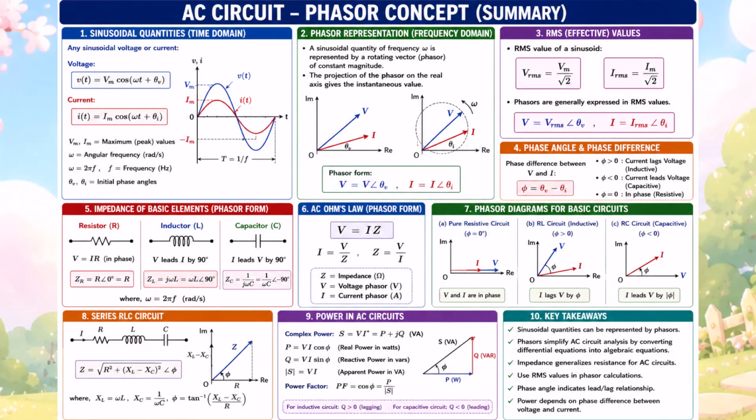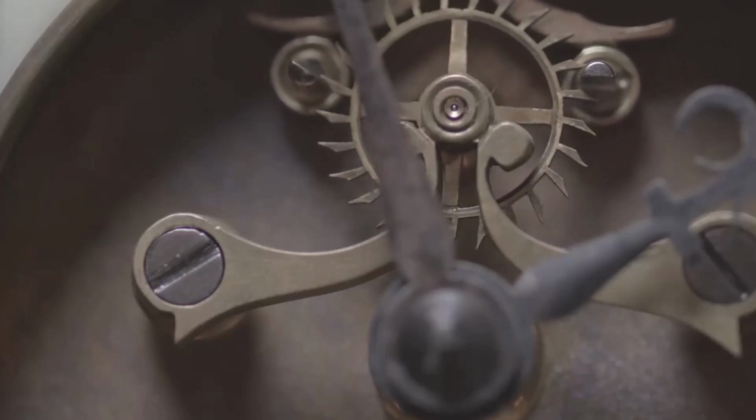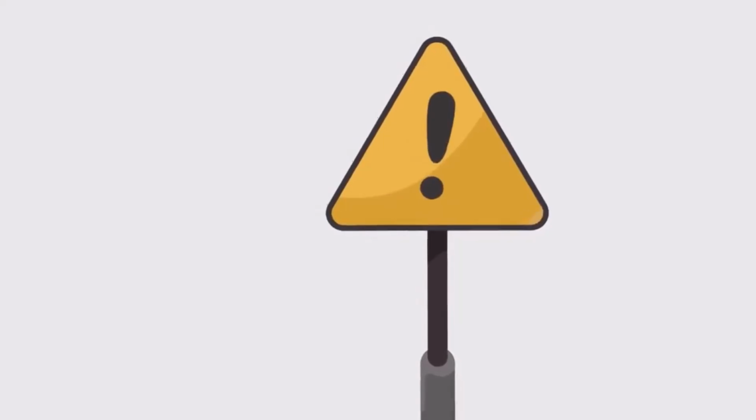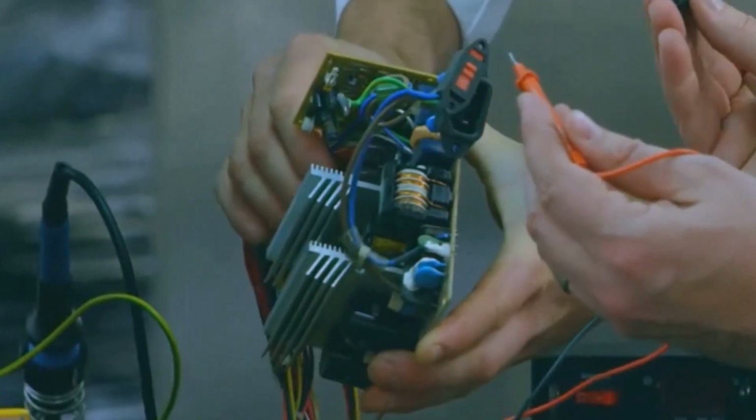The second important piece of information is the direction the arrow is pointing. The angle of the phasor represents the wave's position in its cycle, which we call its phase. Imagine our arrow is spinning around in a circle, like the hand of a clock. As it spins, the height of its tip traces out that perfect sine wave we talked about. By freezing the arrow at a specific moment in time, usually at the very beginning, when time is zero, its angle shows us where the wave starts. This is incredibly helpful when we have more than one wave in a circuit, like a voltage wave and a current wave. Now, let's think about why this is so useful.